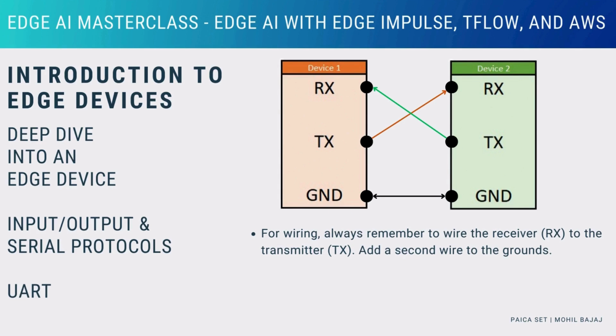If the second device is, say, an LCD screen, then it will not be sending any data back, and in that case, the second TX/RX connection, the green line, can be skipped. Finally, the ground is connected, which completes the circuit and ensures signals are correctly referenced.